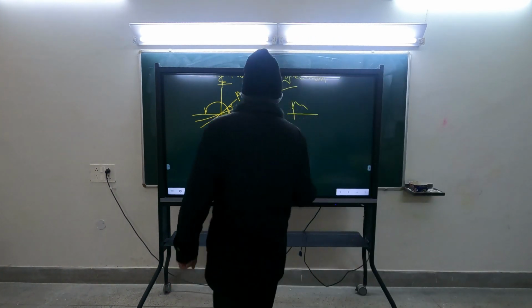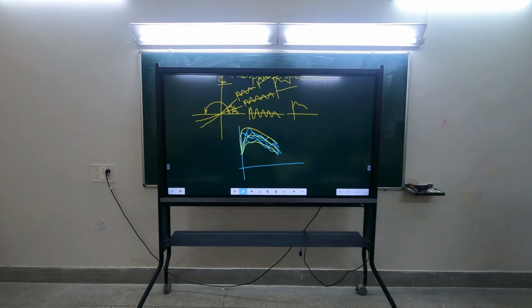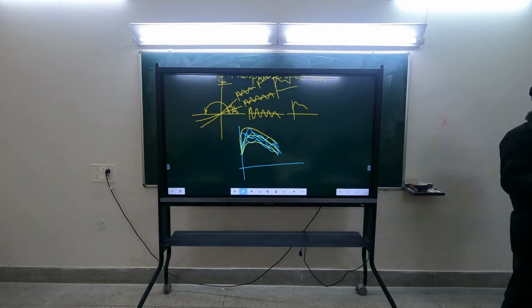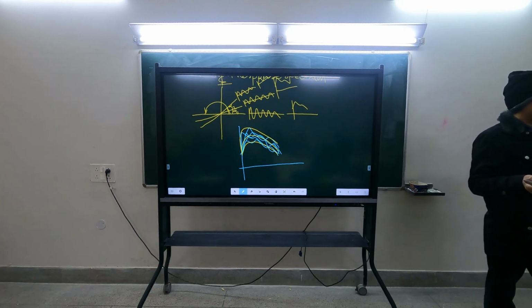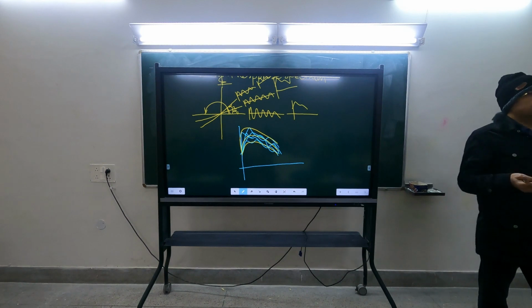You understand this process, what we are doing? The recording is done in two directions only. You need only two ground motion records, and those represent the ground motion fully. It's not that you have to record in other directions also. From those two components themselves, you can generate ground motions in different directions by simple vector resolution. For the ground motion in each direction, you can get a response spectrum. The response spectra are going to be different. At some period one response spectrum may govern, and at another period some other may govern.